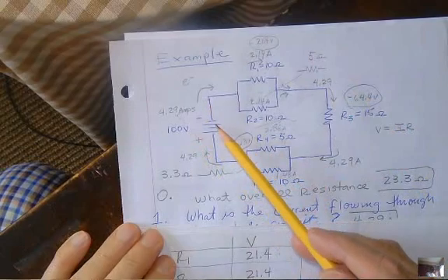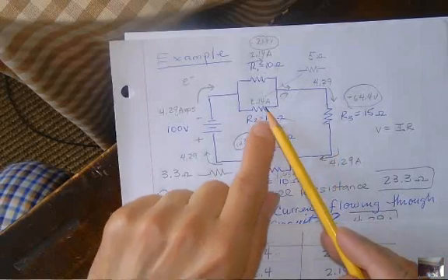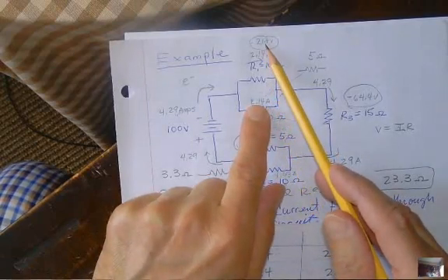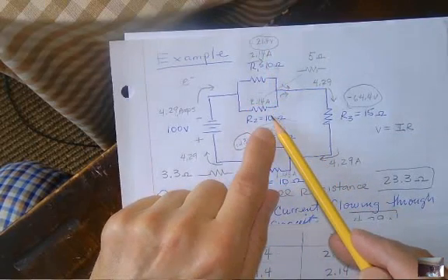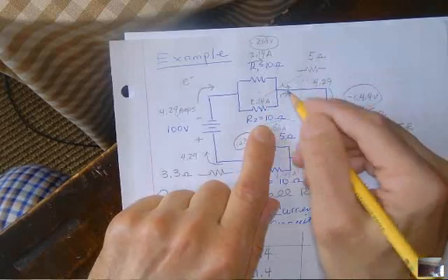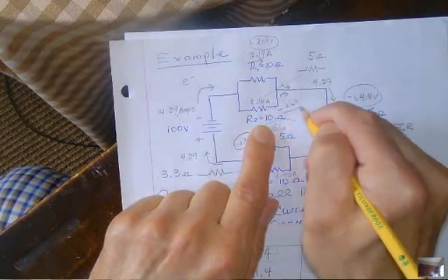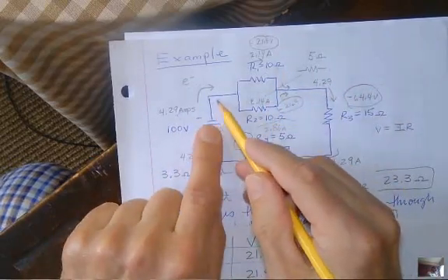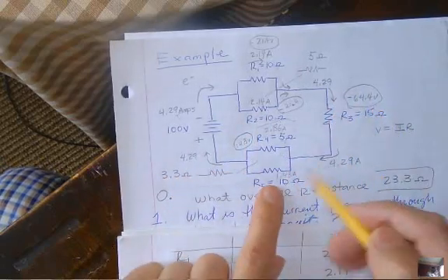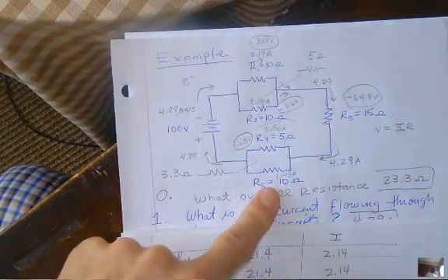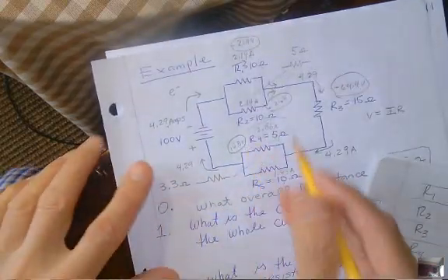Okay, let's go all the way around the bottom. Take this road. Everybody's got to go through there. Take that road. This one has the same exact numbers as this one, right? Remember, they were twins. They had the same current, the same voltage, and the same resistance. So this is also, I got to drop 21.4. So here I come. I got 100. I dropped 21.4. Then I dropped 64.4. Then I dropped down here. What's R5? R5 was also 14.3.